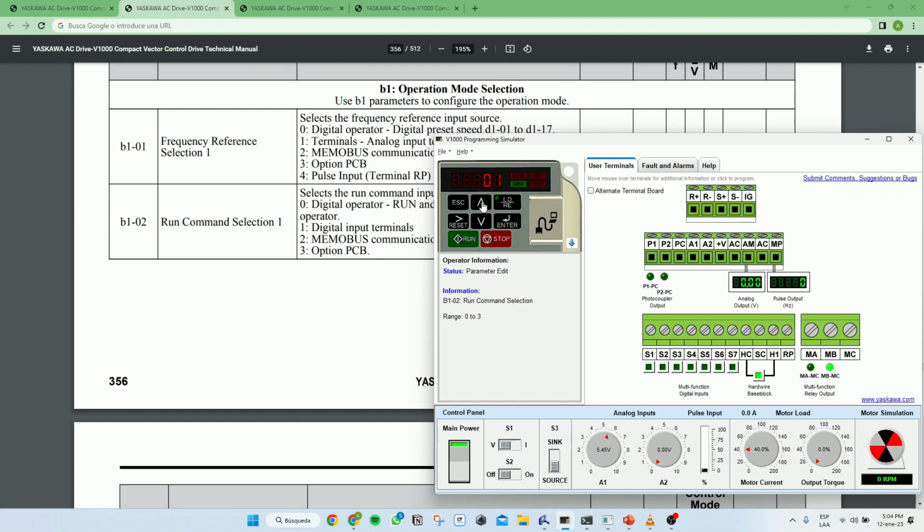The digital inputs. I don't know how the configuration is, but thanks to me adding this part over this button for my mouse, now it's telling me forward run command. And this is S2, reverse run command. So from what I can tell here, simply by adding the parameters which have already been implemented, this is a 2-wire connection. Okay? Guys, don't get frustrated with this.